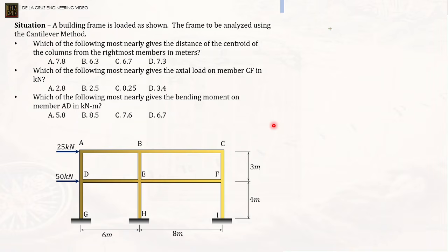In the cantilever method, it is assumed that the axial forces on the columns will be linearly changing, and it will depend on the location of our centroid, either on the left side or the right side. Let's get the location of the centroid of these columns. Generally, the centroid is where the centroidal forces will act because of what the columns can induce.